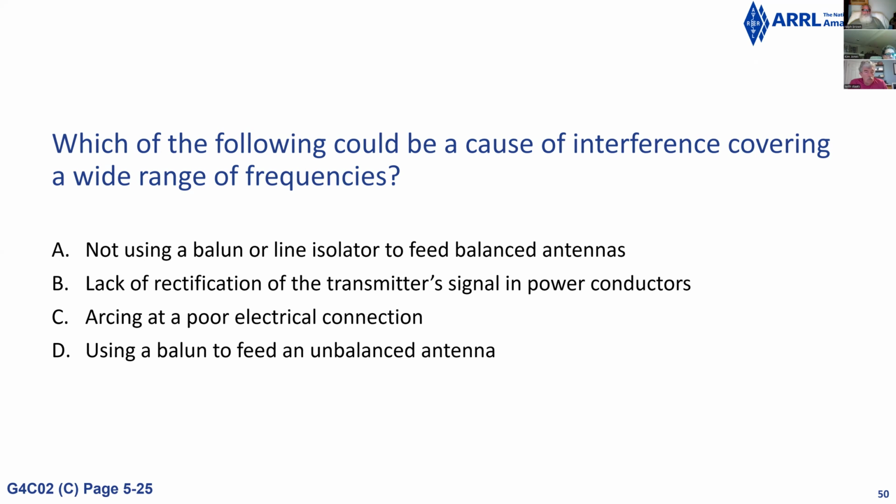I can hear my clothes washer when it's running. I can hear it on 20 meters to the point where 20 meters is unusable. RF being generated by motor contacts that are arcing is being fed out into the power lines in the wall.